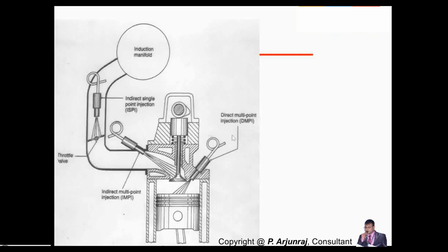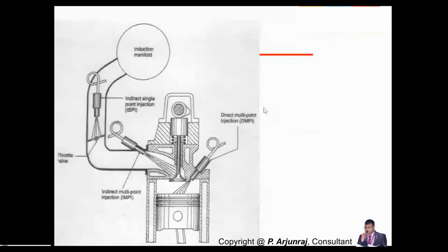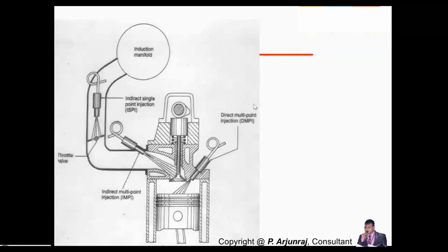And the third important type is the direct injection system, basically the gasoline direct injection system. It can be either a single injection or a multi-point injection. It can be a single injection for a single cylinder engine, and a multi-point injection for a multiple cylinder engine.